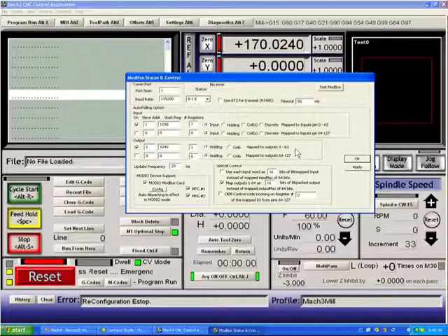So these go out to the ModBus. There's a couple ways they can go out. On a standard PLC control, this is not Peter Homan's board, but on a standard DL5 or DL6, you put a start address of the memory block inside the PLC, and you would say how many registers. If you wanted to use all 63 pins, you would say transfer 63 registers. What is sent to the ModBus control are 63 16-bit words, which are either set to 0 for an output to be left off, or a 1 for an output to turn on. And that 1 or 0 configuration reverses if you uncheck the low active.